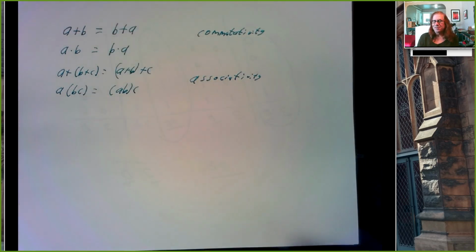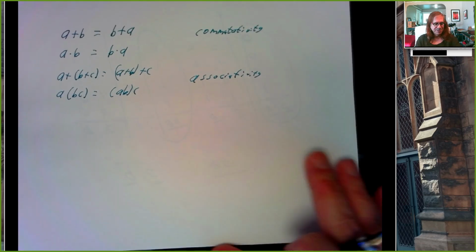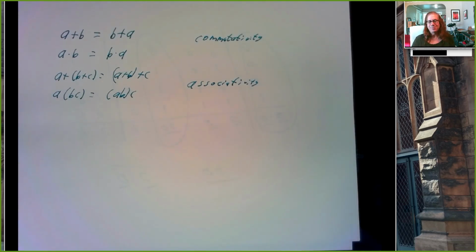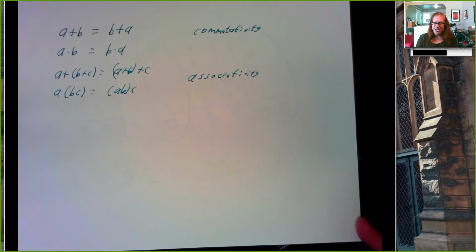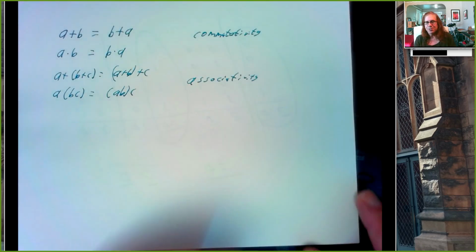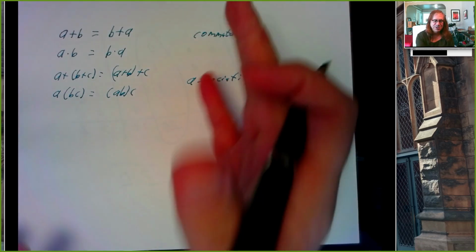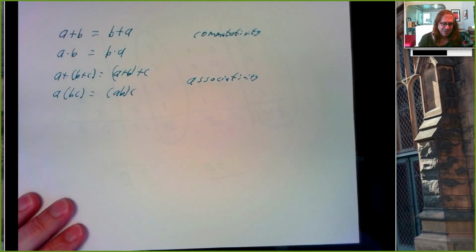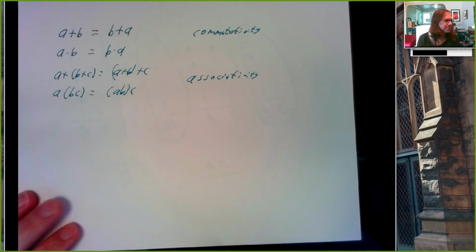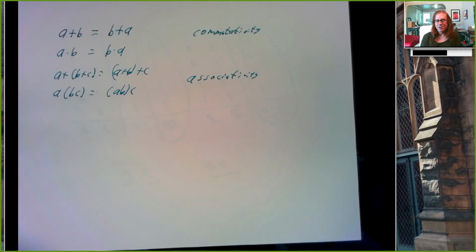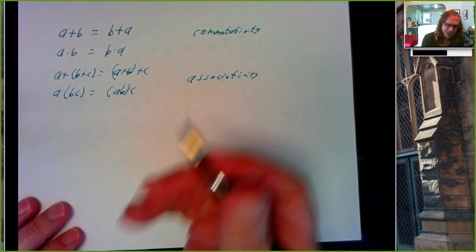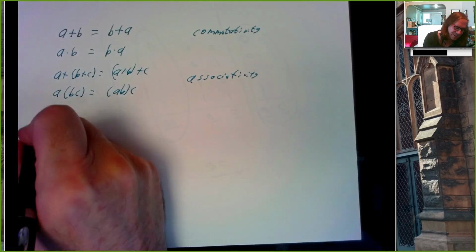And we're familiar with these things from working with numbers, right? 7 times 8 is the same as 8 times 7. If it wasn't, we'd be really surprised. 2 plus 3 plus 4 is the same as 2 plus 3 with 4 added to it, or 2 added to 3 plus 4. And if that wasn't the case, we'd be really surprised, because when we add numbers together, sometimes we change the order, right? If we see a 7 and a 3, we add those together first because we get a 10. Or when we make change for a bill, right? So we're used to commutativity and associativity from dealing with numbers. Well, they also work for logical operations, AND and OR. That's not guaranteed, right? There are things we can describe where these do not work, where they're not commutative or associative. But for these operations, they are.